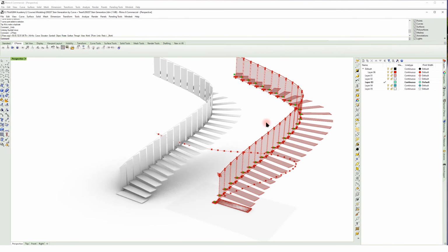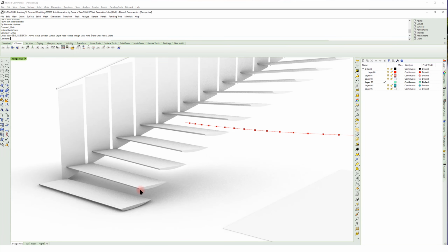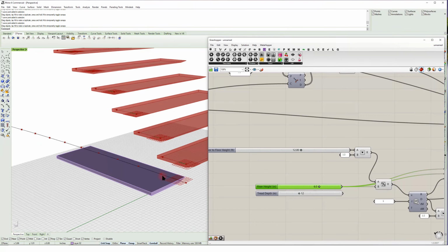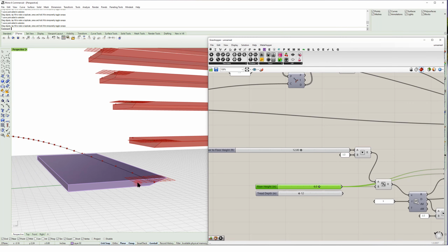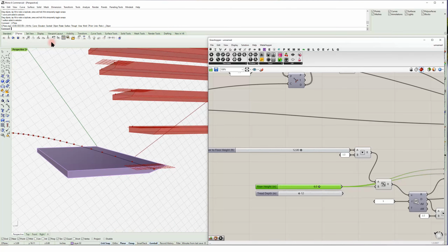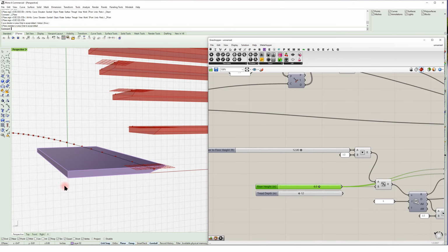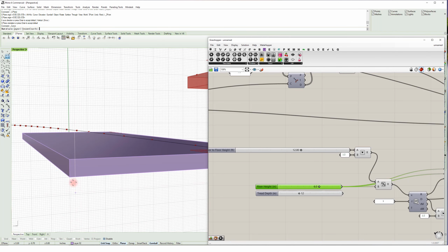So if you remember, we have this custom tread that was basically made by working with that original base geometry down here, and like we showed here, you could Control Shift click, go to C planes and set that to object, or just do C plane by 3 points, and then I basically just model the curve on here and disable grid snap.